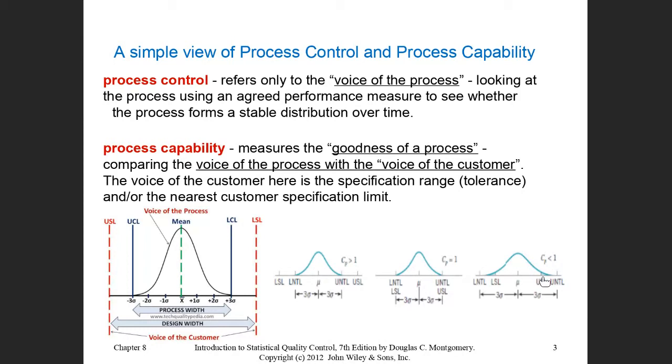Now, what about the control limits? The control limits are slightly narrower than the natural tolerance, or the natural limits. Therefore, it has to be similar to this figure, where the control limit is even narrower than the natural tolerance, and it is narrower than the specification, to perform at an acceptable quality level based on the customer's point of view.